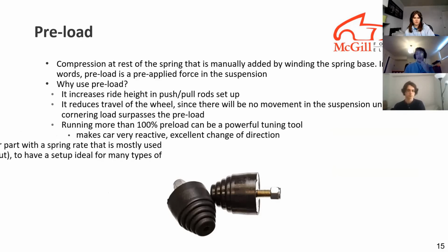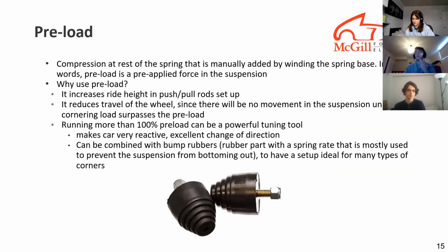Another key aspect of springs is the concept of preload. Preload is an important ride dynamics tool, as it allows us to fine tune how the suspension will react in corners. So first, what is preload? Preload is a compression or torsion that is manually applied on the spring. This means that even at rest, there will be a load applied on the suspension.